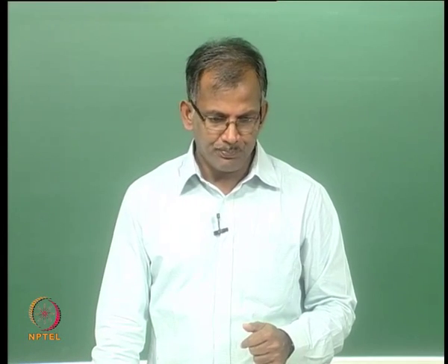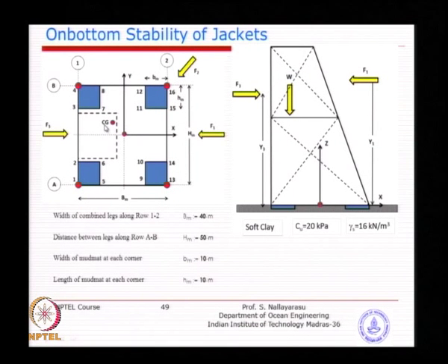So, for a permanent design, without implementing any additional measures for shifting the COG, you design the mud mat system to encounter such a COG. You can see here the COG is shifting towards the west and the north side. So, what we need to see is the point of importance, because that is where the pressure is going to be more. So, all our problem will be associated with this corner.